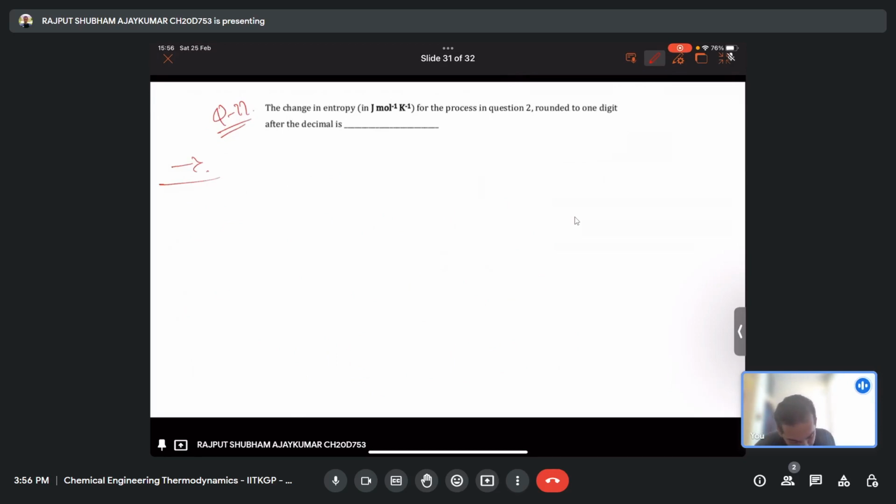So what we do is, for the change in the entropy, this equation also I gave during the start of the session: dS equals Cp dT by T minus del V by del T at constant P times dP, given that P(V minus B) equals RT. As in the previous question, we will try to simplify.